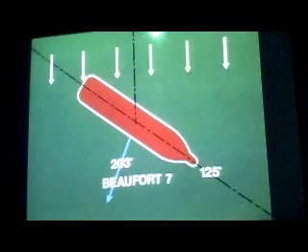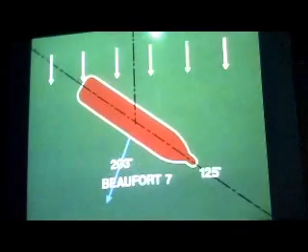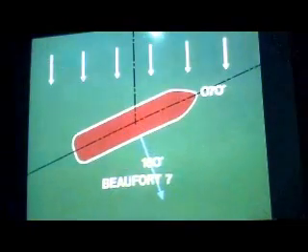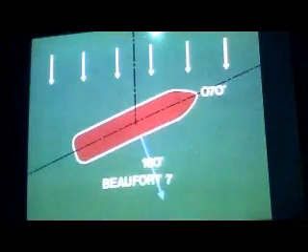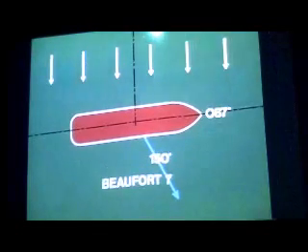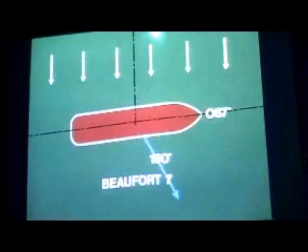Relatively small alterations on otherwise similar hulls can cause quite major changes in the forces operating, and the resulting drift characteristics. For a round bow VLCC in Beaufort 7 sea state, this is a typical track when in ballast. This, when loaded. It is predicted that the vessel would make slight sternway, but in lower sea states, this could become headway. However, the bulbous bow VLCC usually shows headway in both ballast and load conditions in Beaufort 7 sea states.